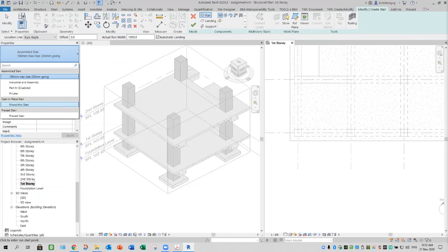The staircase width, I think they only give 1 meter. That's for residential, and the stair flight is 18 risers to achieve that floor height. So it's planned quite cramped, as if 1 person up, 1 person down. But these are worst scenarios, it should not be like that.